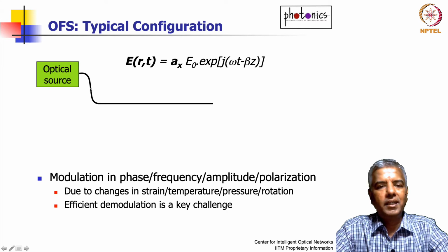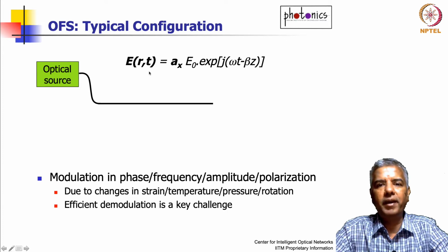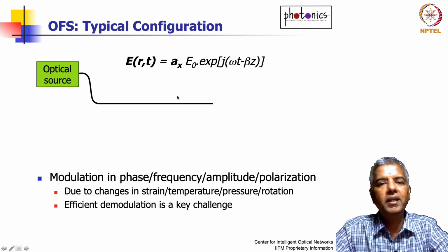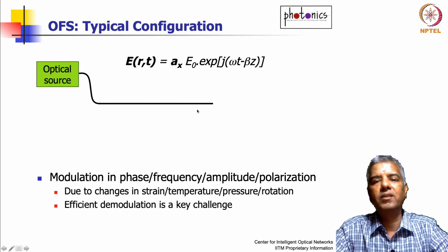When we look at light traveling down this fiber, we are talking about an electromagnetic wave propagating down this fiber. If you look at the electric field component of that wave, it is going to be defined by several parameters. The popular one is the amplitude of the electric field, and this defines the intensity of the light propagating down the fiber. That's the most apparent, but it also has polarization associated with it. Here I'm saying that this is an electric field polarized along the x direction, and the propagation is along the z direction, along the length of the fiber.